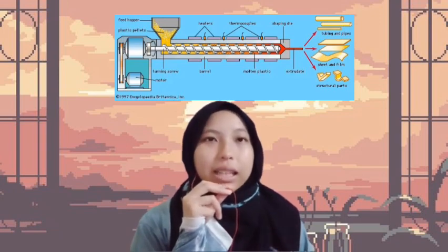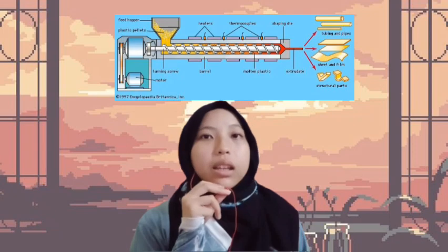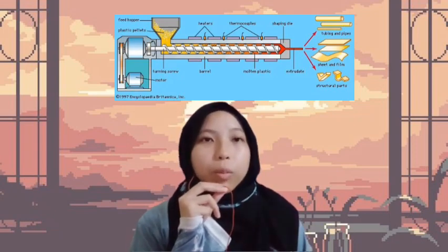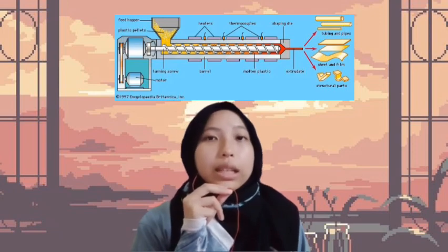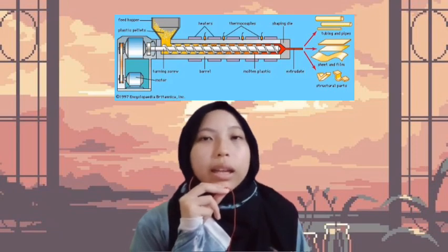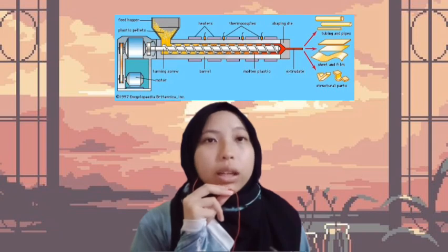The viscosity decays with an increasing shear rate. The process employed in the fabrication of the melt flow rate meter involves marking pipe for the barrel and cutting to size, machining a cover plate, and welding.